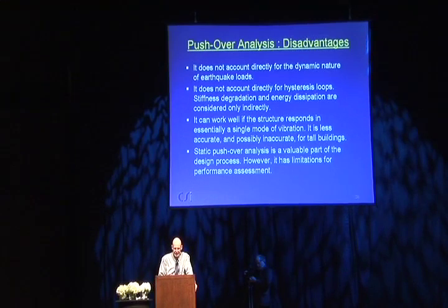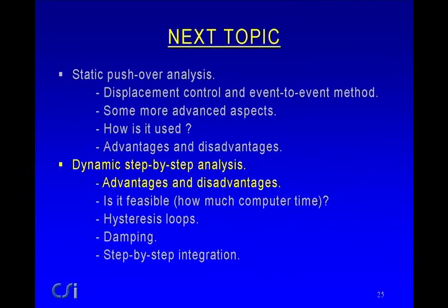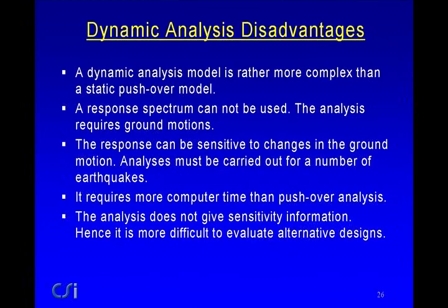Static pushover analysis is a valuable part of the design process, but as a method for performance assessment, it does have limitations. Let's move on to dynamic step-by-step analysis and start off with advantages and disadvantages. Disadvantages: the dynamic analysis model is rather more complex than the static pushover model. Not a lot, but some. You can't use a response spectrum, you require ground motions. The response can be sensitive to changes in the ground motion, sometimes rather remarkably sensitive, unfortunately.